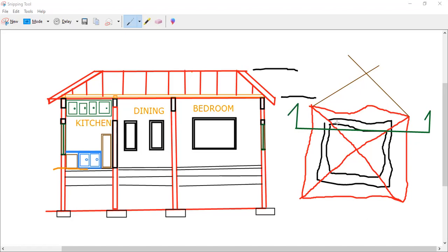At the point where the cutting plane line touches the rafter, you would bring that point up to cut the corresponding rafter. Then you would bring this line across here, and this goes down to that. So the roof is formed right here. This is basically the outline, the shape for the roof.